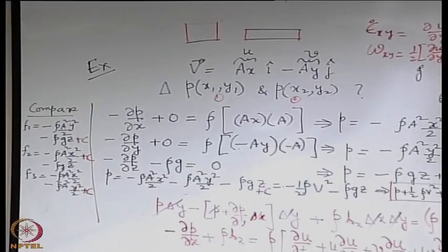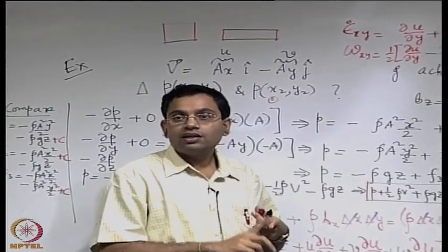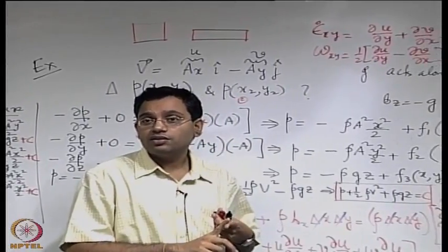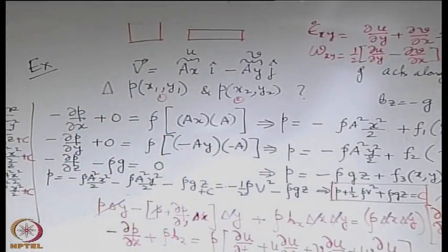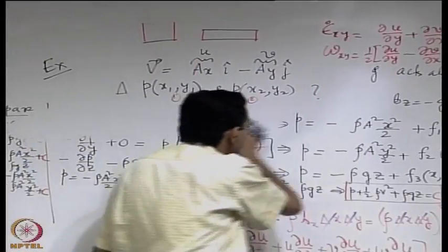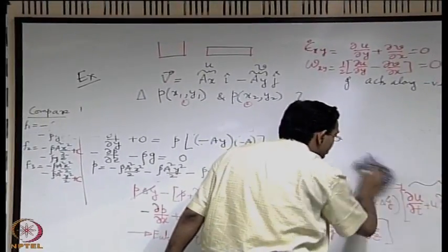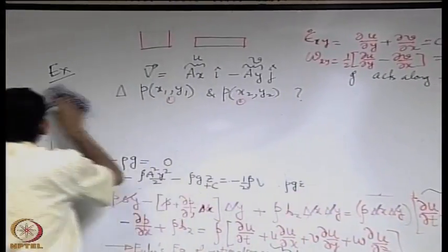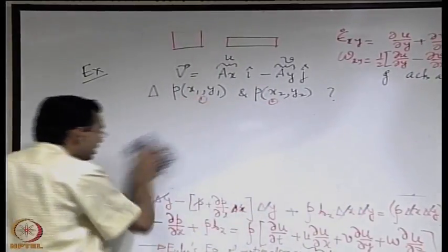So it is an incompressible flow. So that is one important observation. The important observation is it does not have any shear effect. Next, it does not have any angular velocity, so it is like an irrotational flow, because an irrotational flow has no angular velocity or no vorticity, so to say. Now let us try to see what will be the equations of the streamline in this case. So we are interested to find out the equations of the streamline. It will give us even a deeper insight, and we will relate it to one of the movies that we saw in our previous lecture.